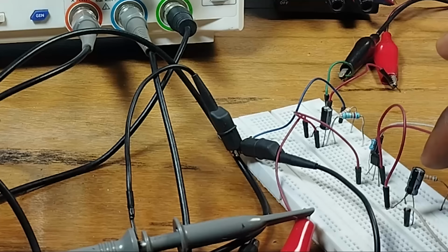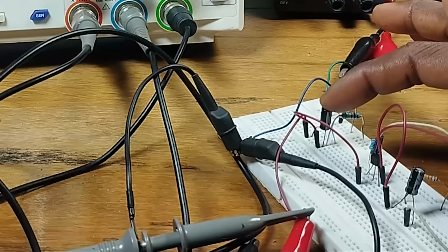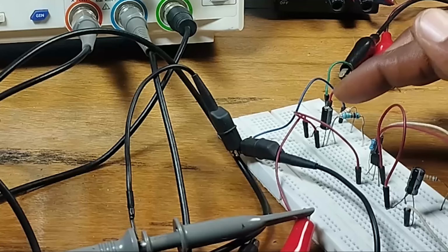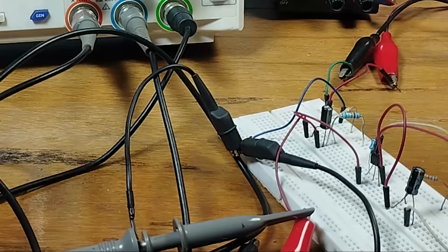You can see the positive pin is on the collector while the negative pin is on my output, because the collector voltage is higher than the, of course there's nothing connected to the output here, so it should be the positive voltage on the higher potential. While for the input capacitor, which is this one, we have the positive on the voltage source coming in, and we have the negative towards the base.